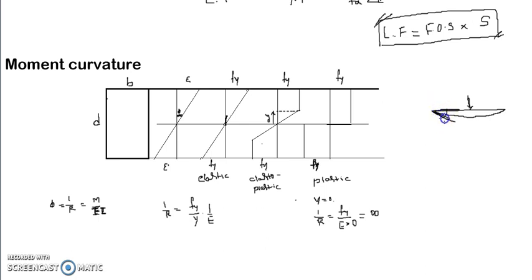Now if you go on loading, once the plastic stage forms where the bending moment is maximum, this becomes a hinge.